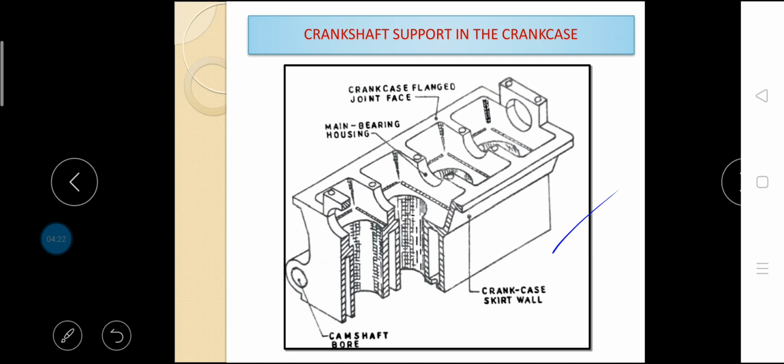However, it has the disadvantage of more wear, to obviate which cast iron liners have to be used. Besides this, the threads in aluminium are easily damaged in case of any mishandling. Further, since it cannot stand high temperatures, unlike cast iron, there are more chances of damage occurring in case of any loss of coolant. Aluminium alloy cylinder blocks with chromium plated cylinder bores have also been used to obtain a lightweight and less wearing surface.